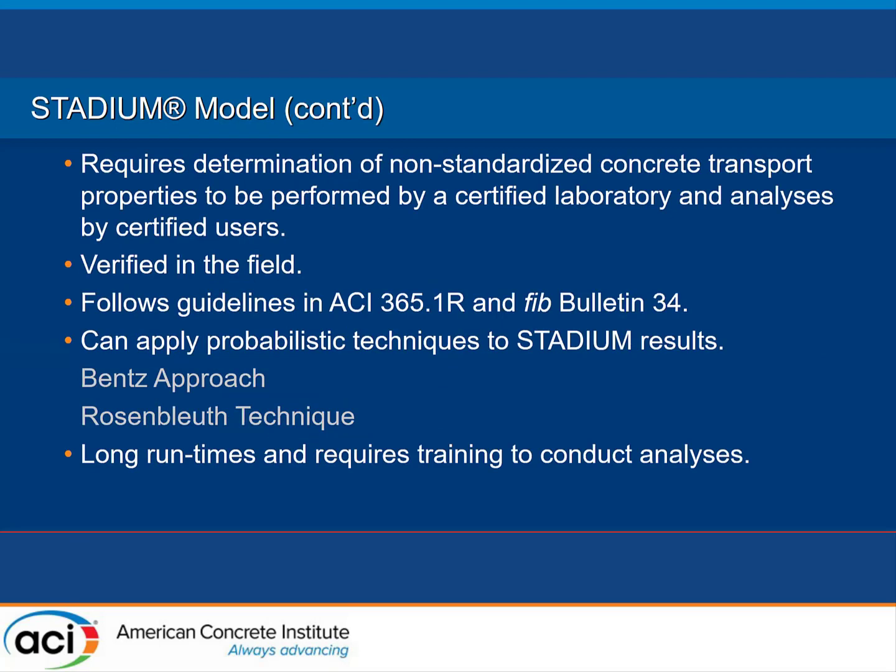It requires determination of non-standardized concrete transport properties, and these need to be performed by a certified laboratory, and the analyses are by certified users. It has been verified in the field, follows the guidelines in both the ACI 365.1R and fib Bulletin 34. You could apply probabilistic techniques to STADIUM results.